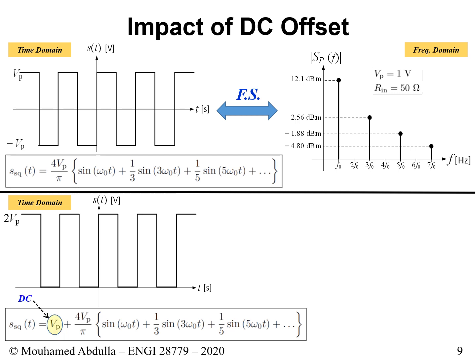Like I mentioned to you, this is referred to as the DC component of the signal. So now if you look at the signal, right away, you know it has a DC component. By the way, a DC component could also be detected right away visually by simply looking at the graph. Using the trick of knowing if a signal is even or odd is always good to determine if there is a DC component. So here, I know the signal is odd, so certainly it will not have a DC component.